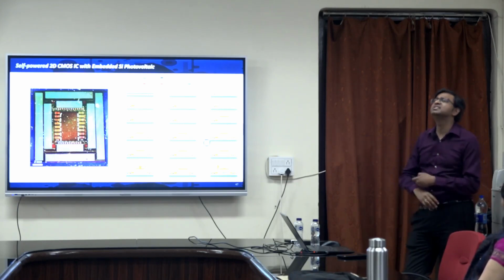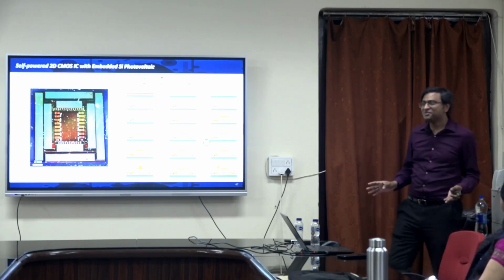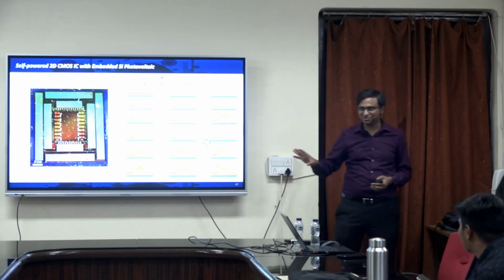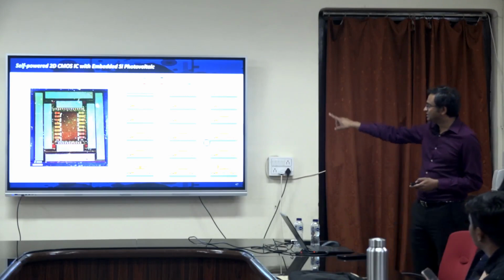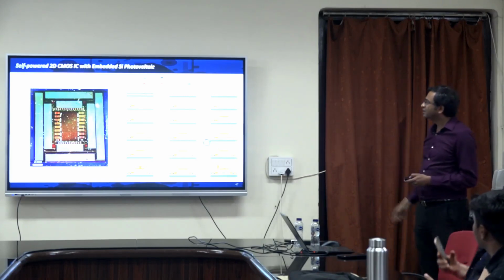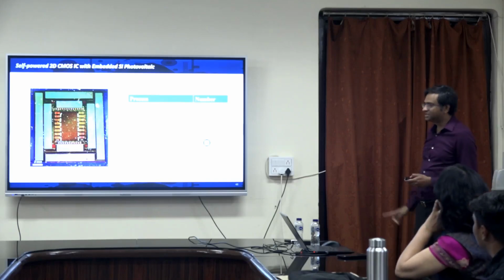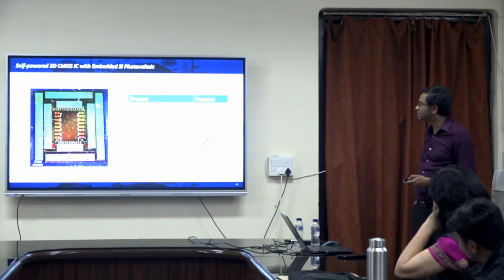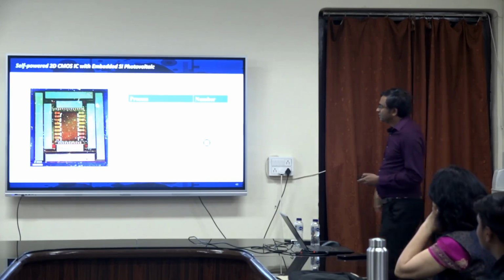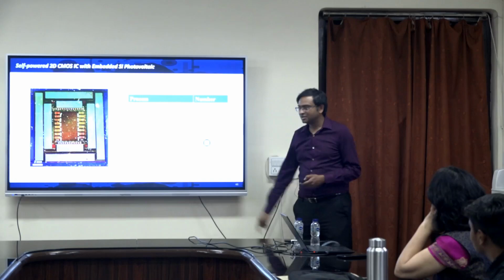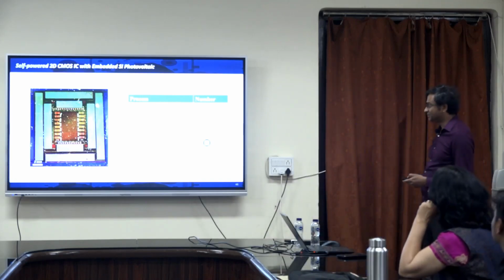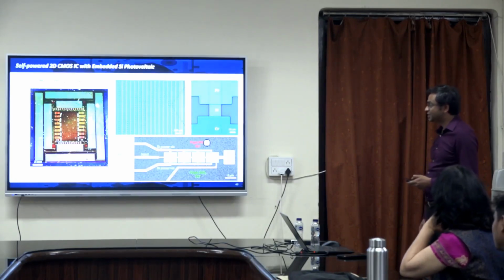Now the fabrication is even more expensive, right? First you have to make the silicon photovoltaic, and on top of that you are making all this 2D CMOS. You see these are the fabrication steps. A lot of materials over there. This is just one tier. This is the number of e-beam evaporation steps. So how much did you count? 6, 18, 28 and 35 lithography steps, and then we get to it.